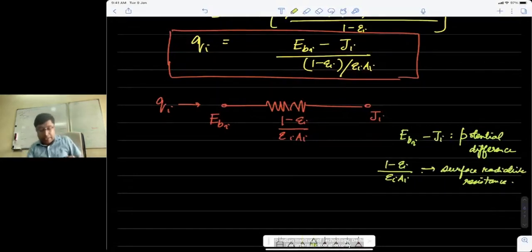Don't go by the units that we used in conduction. In conduction, we had temperature as a potential, and the resistance was because of the conductivity, or in convection because of the heat transfer coefficient. Here we have a different form of writing these potentials and resistances, but the idea is the same: there's a heat current which has to flow through a certain resistance between two potentials.